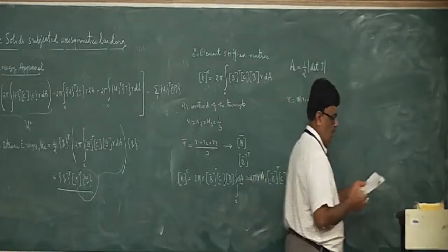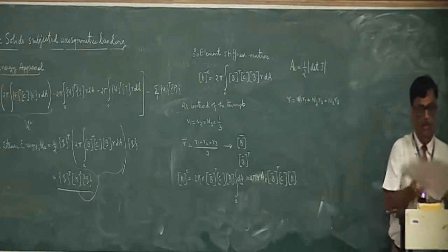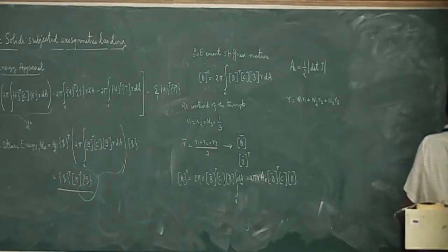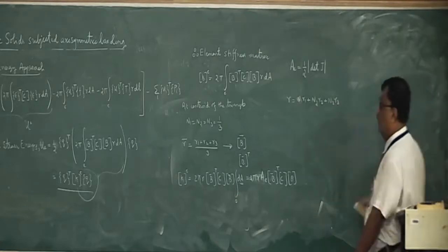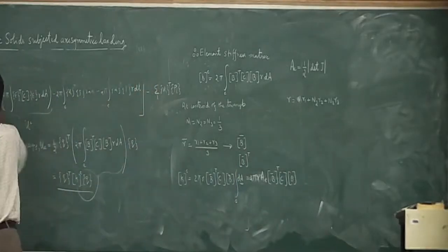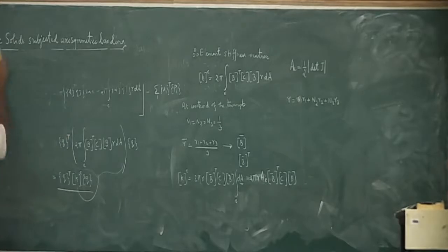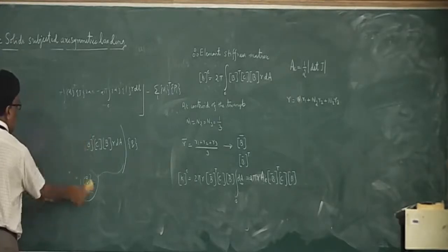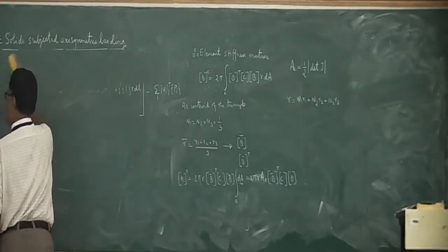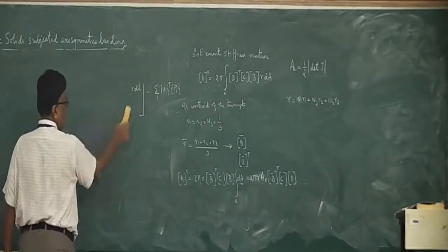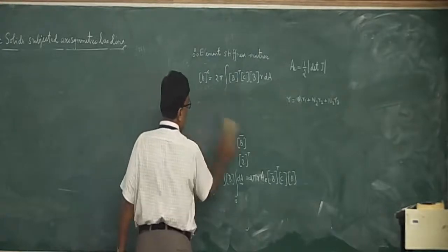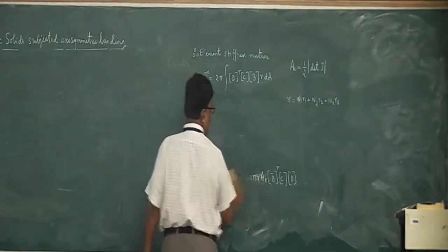So it depends upon where exactly we are going to evaluate our element stiffness matrix. If on an average we take it at the centroid, then R will be found by R1 plus R2 plus R3 upon 3, and then we take the routine calculations with that R. Otherwise, if you want some other specific points, then R needs to be interpolated with the help of those shape functions which are already given.